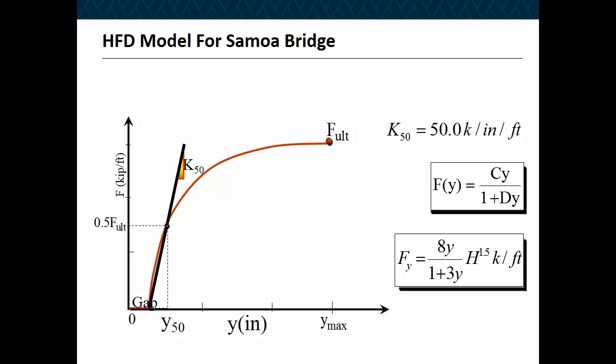But of course, many abutments also have a gap. Now, here is a trick. In the finite element model, you can either use a gap element and then put the nonlinear springs, or make the gap part of your backbone curve. Another way, your abutment spring would be flat, and then it goes to nonlinear.